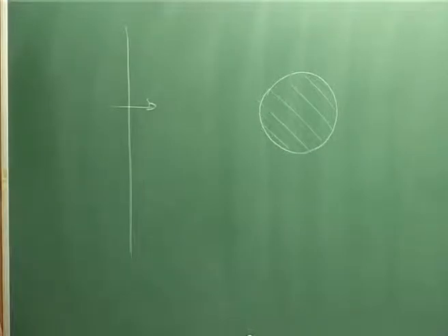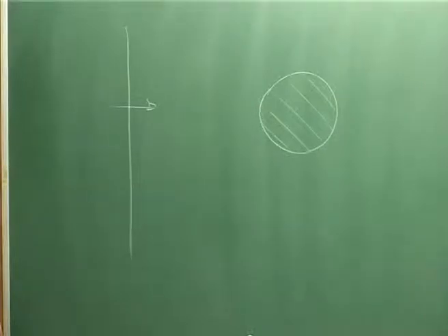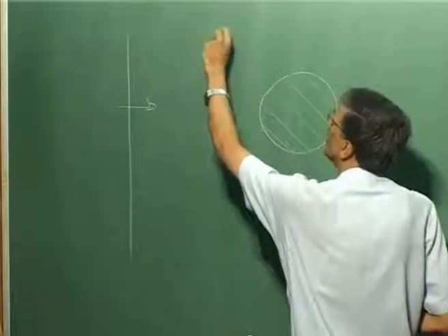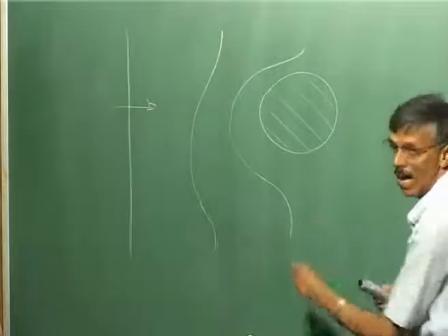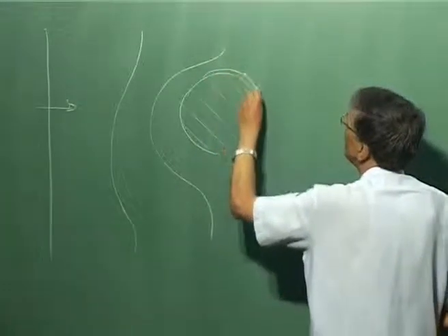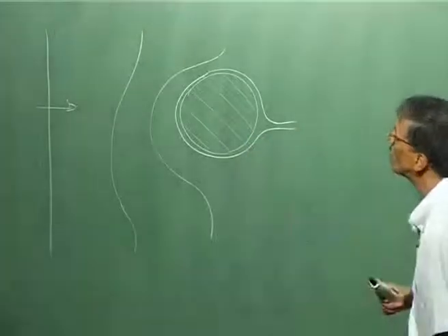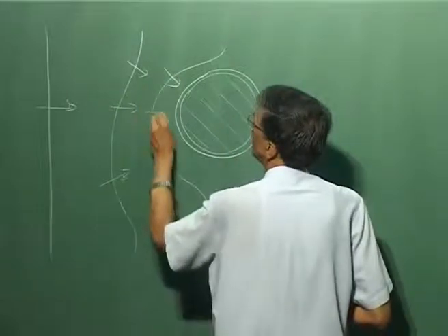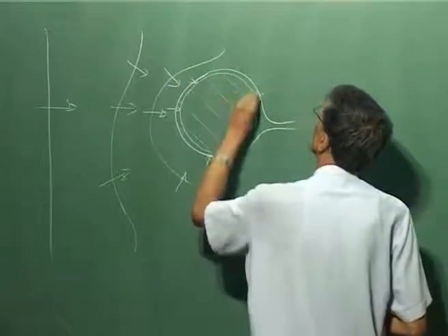As you can see, again, if we consider that the depth is increasing in the radial direction, then as the wave comes closer, it will start bending, and when you are in the very near vicinity of the beach, you are going to see the crests going like this. So, you would be getting the crest directions like this, and here you can see that this is going to happen.